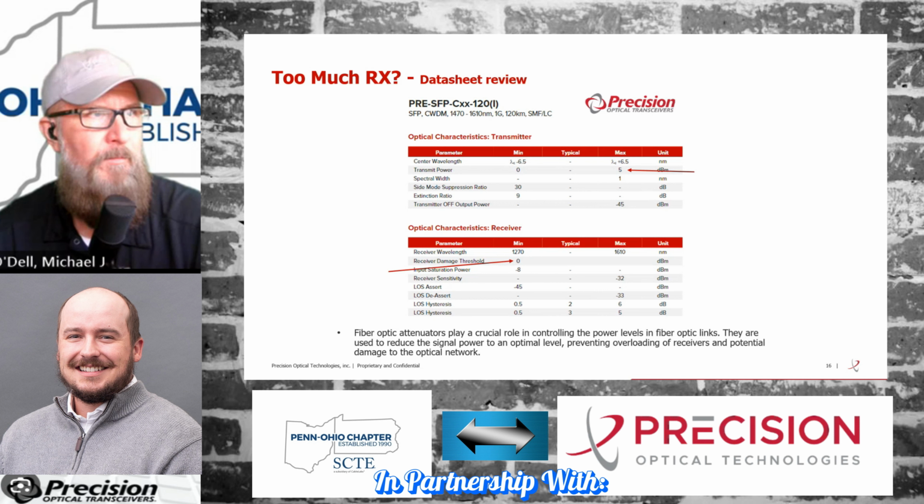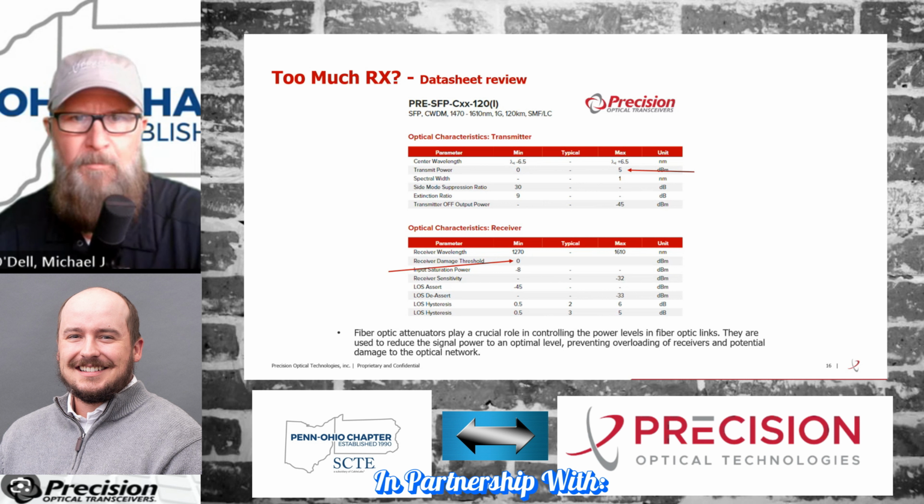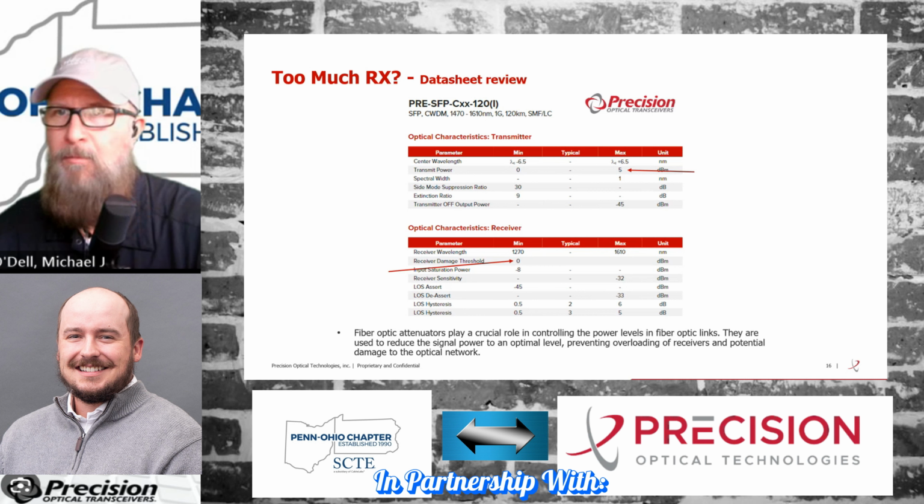However, you see here though is the transmit power minimum is also the same as the receiver damage threshold. So if you ever are plugging a signal into a 1 gig DWDM or 1 gig CWDM optic, you want to make sure it's gotten some optical loss over that fiber. Otherwise, you do risk receiver damage, where you actually just completely smoke the receiver, and now you've got a hat weight, not a transceiver.